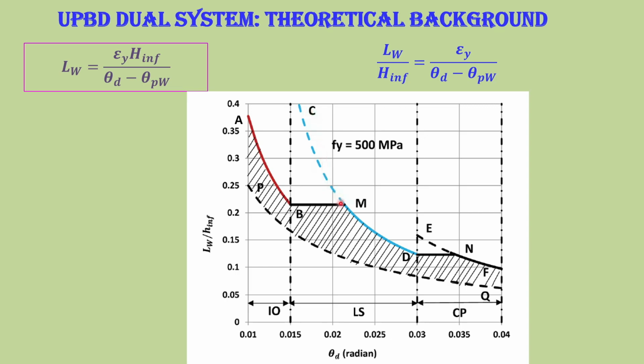discard. So C to M I shall discard by drawing a horizontal line from the point B. So BM is a horizontal line, and CM I discard in the LS category of buildings, and the remaining line MD will give you the LS range, including from B also. So under curve BMD, whatever is hashed will be LS buildings.